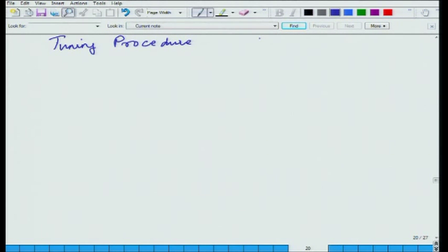Okay. Let us say I have a 2 by 2 system as an example for the tuning procedure, so I have 2 controllers which we have been looking at. Obtain Kc, for example Ziegler-Nichols, and the reset time tau I Ziegler-Nichols for the first controller.